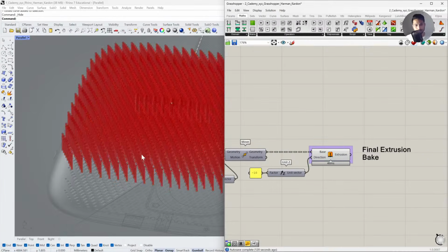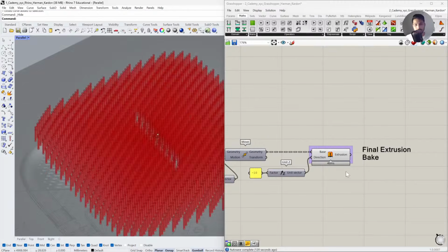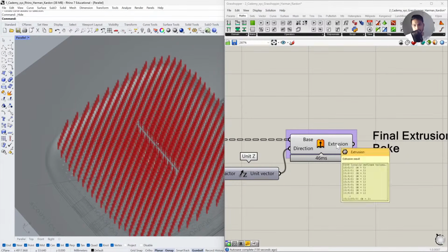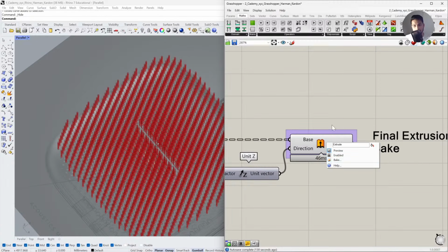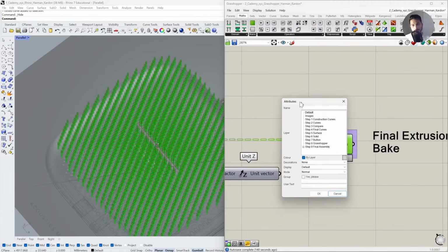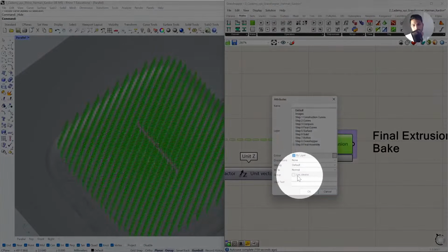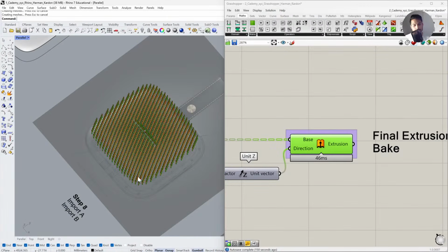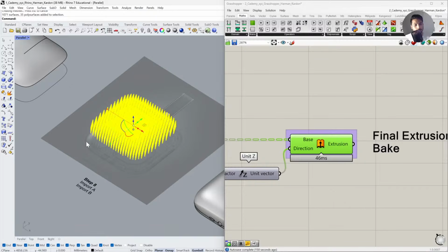Alright, so if you are in your Grasshopper canvas, you can get to this part, make this part visible, okay, and you need to convert this geometry now into a Rhino geometry. Okay, so in order to do that, you right click on it, on the component, and there is this option called bake. Okay, it's better you use the right click option rather than the middle button option. Okay, because when you right click and bake, you're able to group the objects together. So let's group, bake it, and here you have the extrusions.